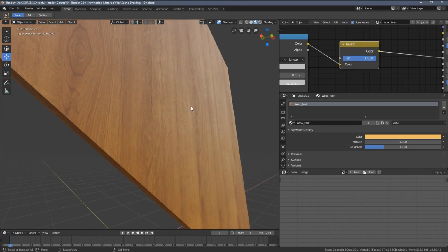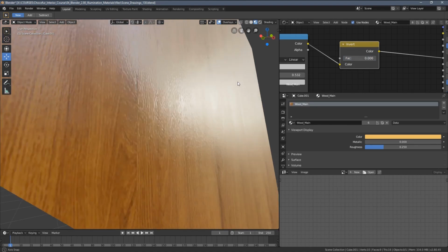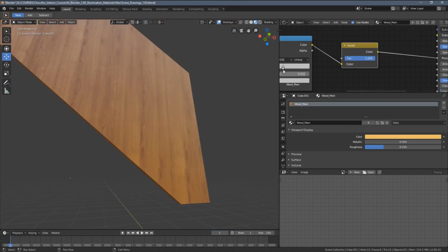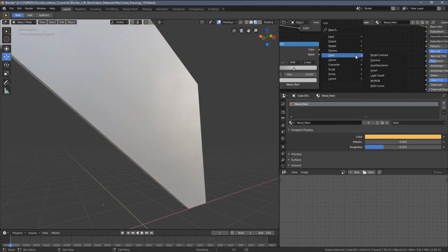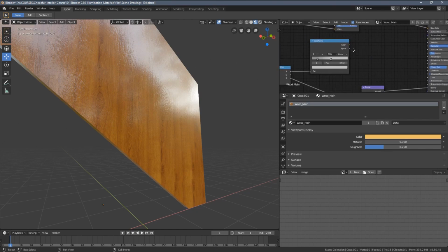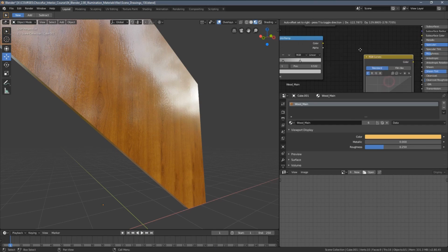We would simply like to invert the effect we had here, but with the invert node, it actually changes the values of the color. So the way I'm using to invert my reflection setup, I already have here and here. I'm using the color RGB curves.